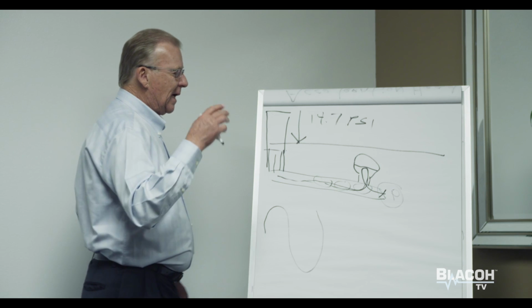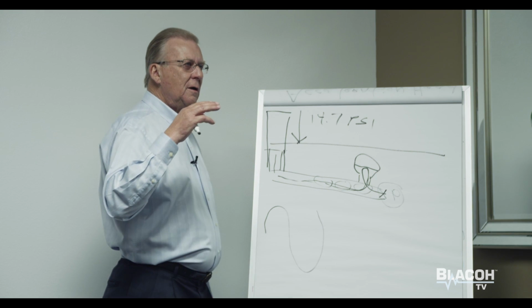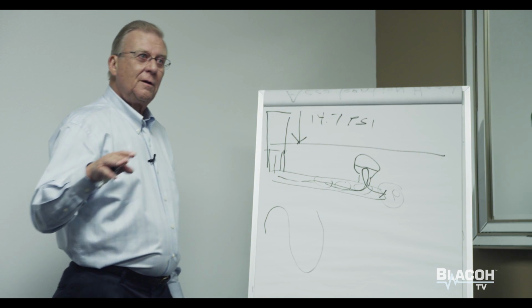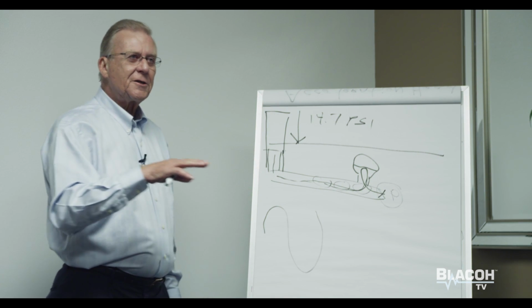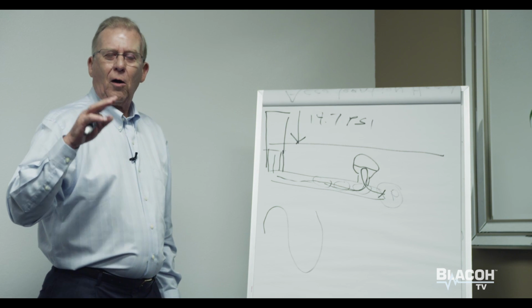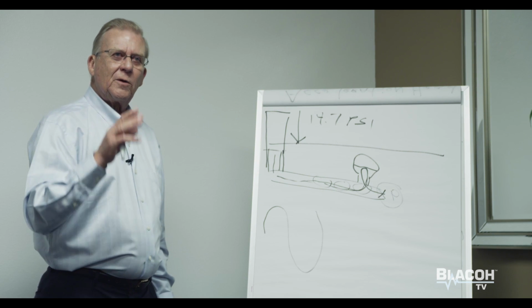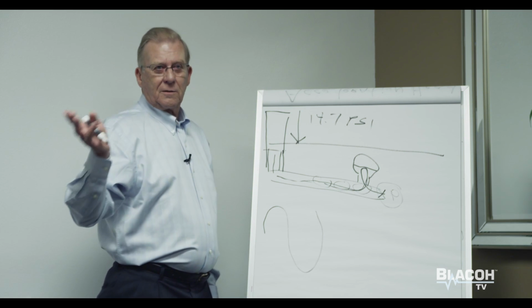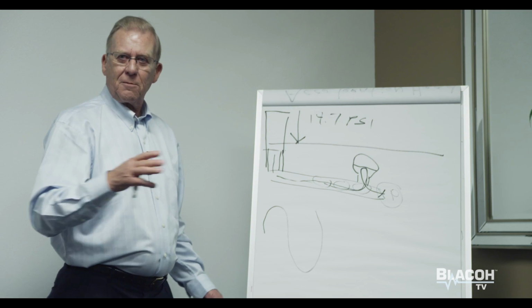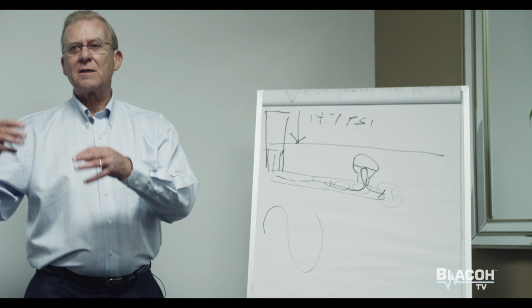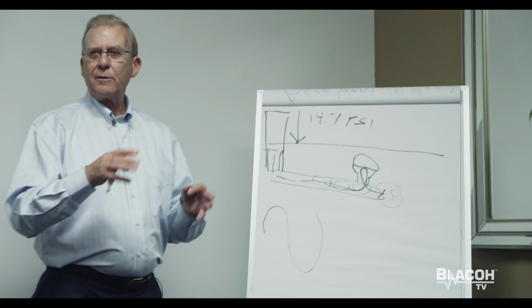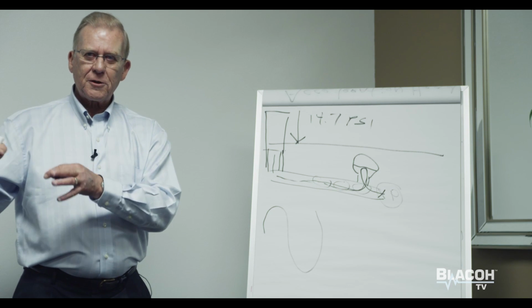Okay? But many people who do these calculations to ultimately determine what the total dynamic head of the system is, total dynamic head basically is all of those components, the friction loss, pipe size, elbows, all the other things, to determine what size pump is needed to produce the flow at the discharge pressure required.